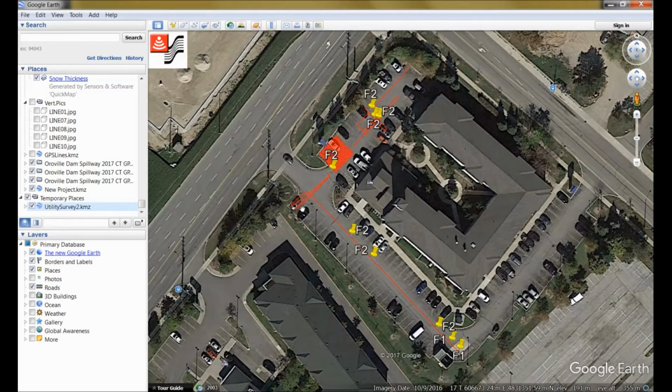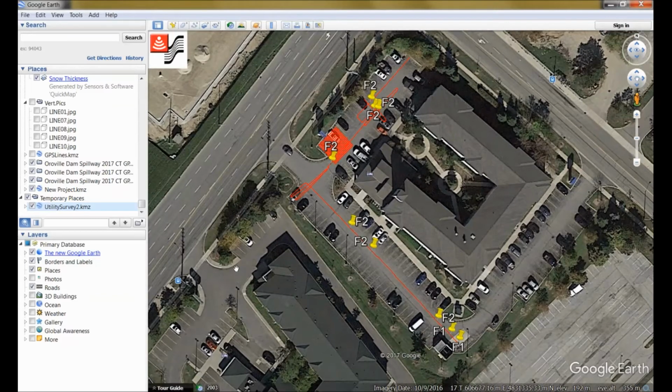Note that the position of the GPR line paths are only as accurate as the GPS. So if you see the path going over a building or somewhere where the GPR data was not collected, it's because the GPS receiver became inaccurate after losing satellites, typical while working around buildings and tree cover. In this example, if you look at the red lines indicating the GPR path, we can see the GPS is pretty well behaved because the survey was collected in an open area.